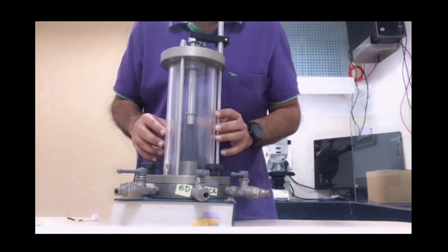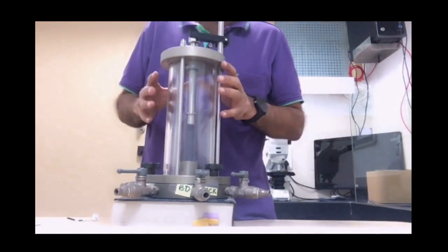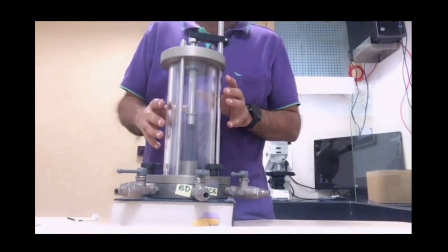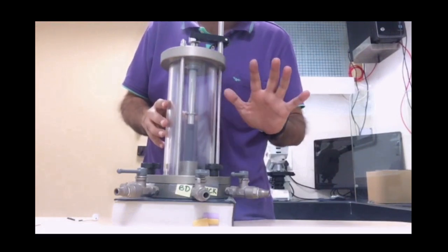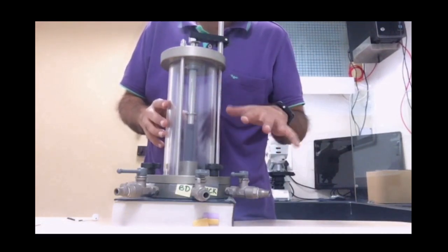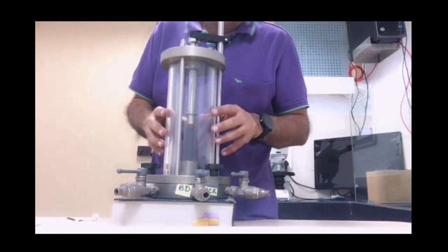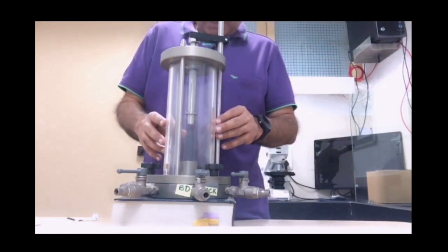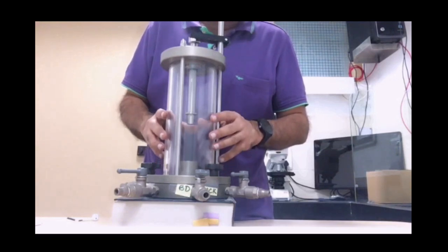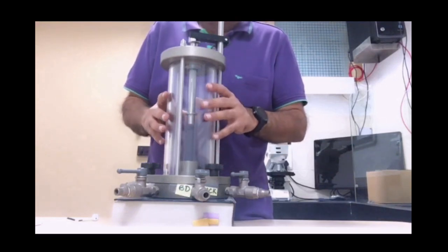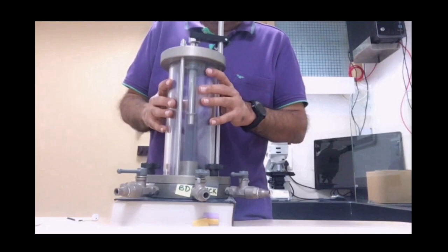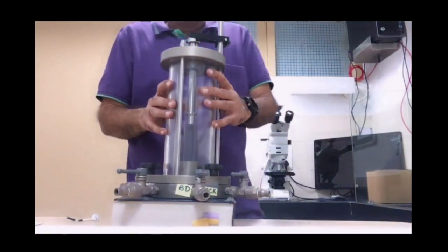So 345 within the sample, 350 outside the sample. So the effective stress right now is just about 5 kPa. It's not going to harm the sample significantly, because it's not going to disturb the sample. This value of 5 kPa which I have chosen is significantly less than the final consolidation pressure which I will desire at the end of stage 1 of triaxial.